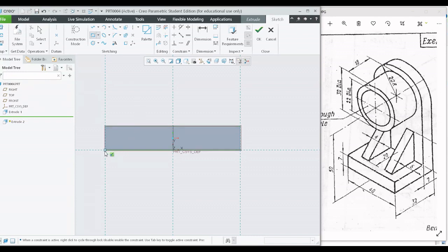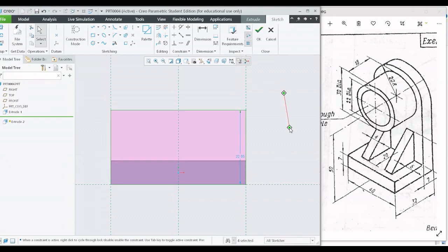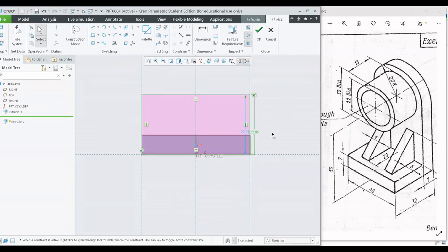Select on the rectangle option and match the width. Stop at certain position. So this particular distance, that is the base till the central point of the circle, is equal to 50 units. So let me double click and change it to 50 units.